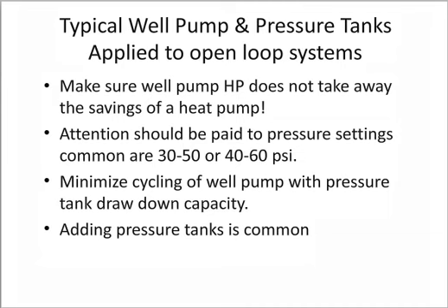You want to pay attention to the pressure settings. Typically, they're 30 to 50 or 40 to 60. The lower pressure is when that pump's going to turn on, and of course, the higher is when it's going to shut down that well pump. You want to minimize that cycling of the well pump, because with a lot of electric motors, the real large energy consumption and draw is when it goes to start. So you want to pay attention to that, and it's fairly typical that you need to add a couple of pressure tanks, 1, 2, or 3. It really depends on that application.